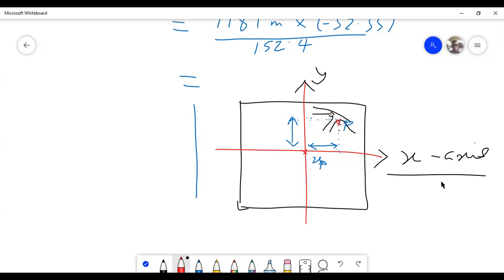The origin. Okay, so it's 0, 0. So we can now measure from the center: going to the right is positive, going upwards is positive, going down is negative, going to the left is negative. So we can get a coordinate here for point C, and the coordinate will be negative. Are you okay? If you get 10 millimeters here, that's minus 10. And you have to bring the minus 15. That means 15 millimeters. Are you okay? All right. So that is the way it goes.